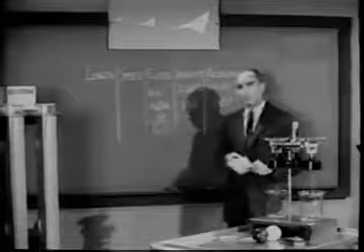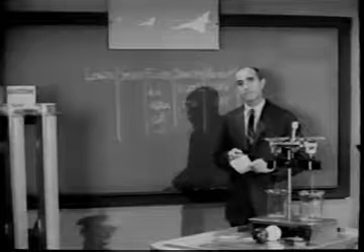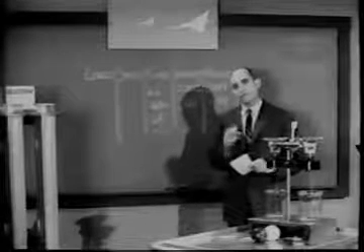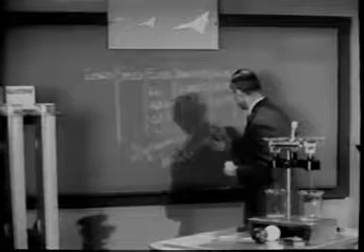Suppose that in two of the experiments, the several quantities in Newton's force balance bear the same ratio to each other. Then those experiments are dynamically similar. And from the point of view of mechanics, they are in a sense identical experiments. Now, different experiments are dynamically similar only if a special combination of these quantities is the same.